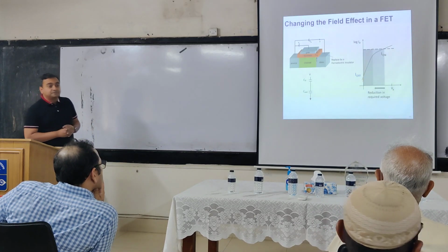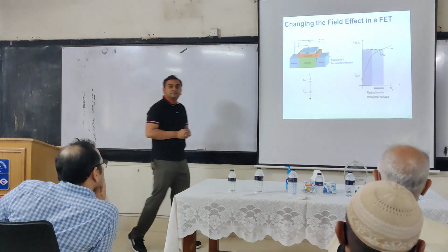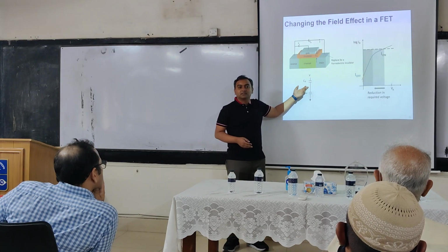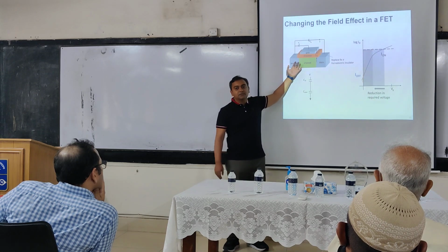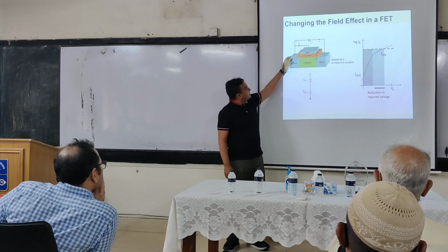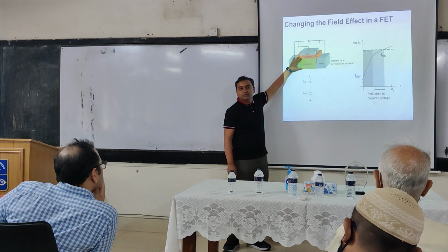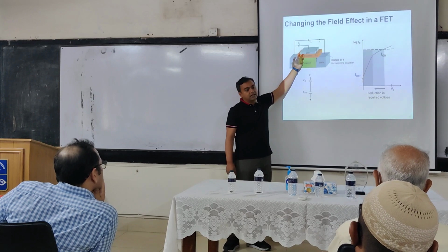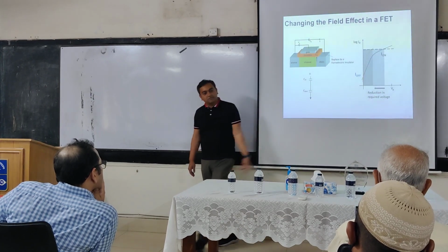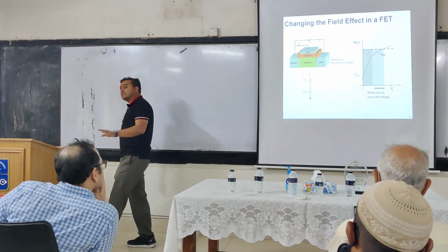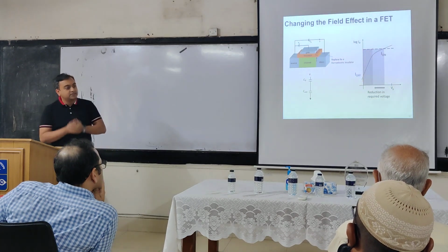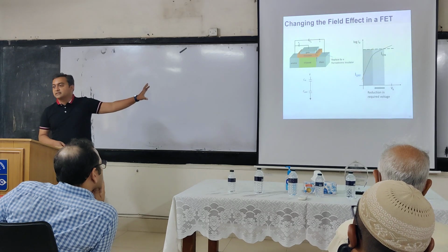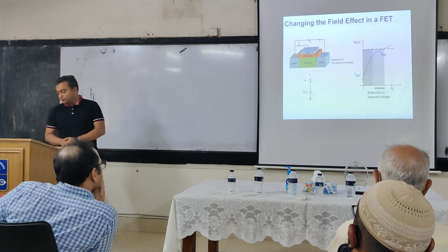The great thing is, in a transistor, it turns out this series network that I needed, a series network of two capacitors, is present by design. A transistor has this semiconductor channel which has its own capacitance, and it uses a dielectric as a gate. If I can replace the dielectric with a ferroelectric, it automatically produces that series connection. I am really simplifying it here because you have to have material compatibility. I'll talk about that. But conceptually, this is it. That's how we can get there.